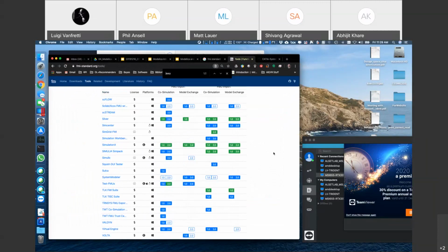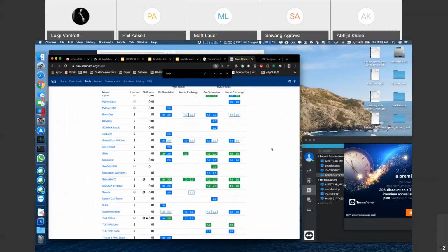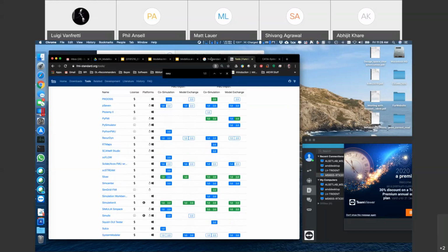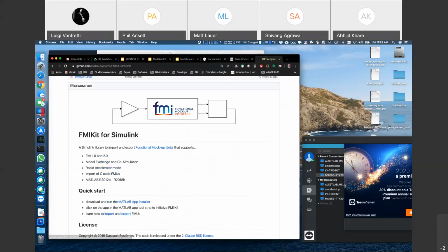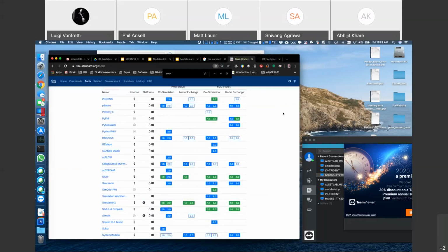I can give a class on that if you want me to. I need to expand the materials, because my materials are made not to do something so complicated. But if you use this open source tool, for example, or the FMI toolbox from Modelon, both of those tools allow you to export a model as an FMU to be used anywhere else you want, not just Dymola. You can use it in Python, for example, for scripting and so on.